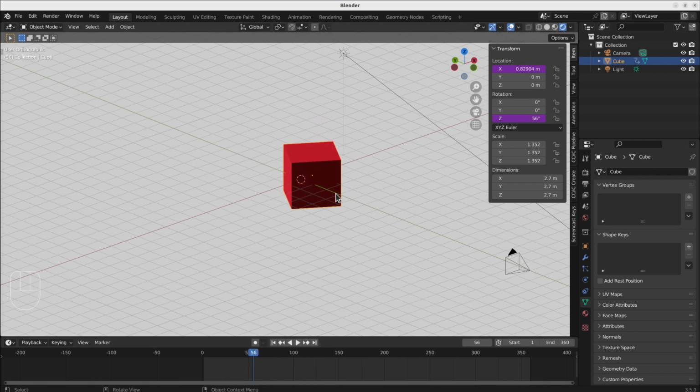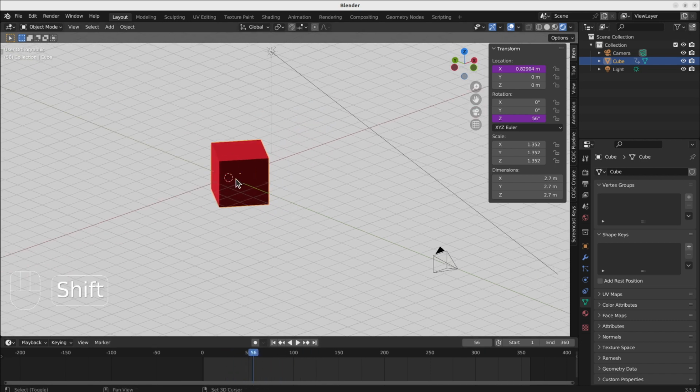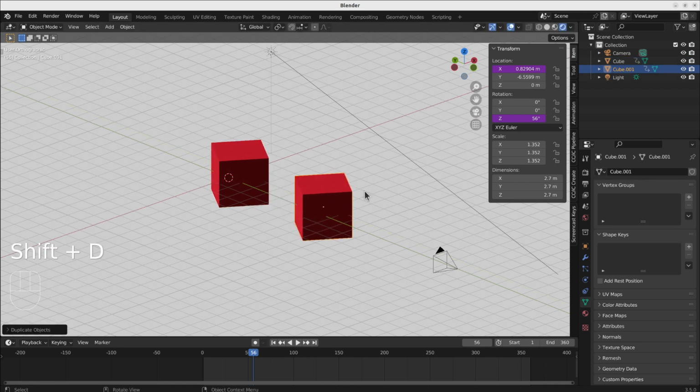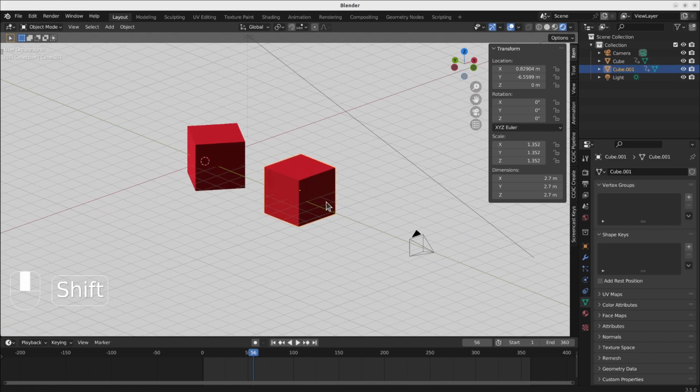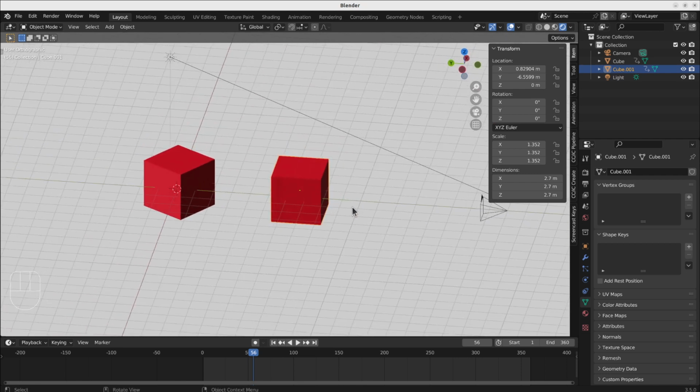Let's make another cube and use another scripted expression. Let's delete these drivers and let's turn it to 0 again. And now let's make something like going up and down by using the modulo function. Frame modulo 10.